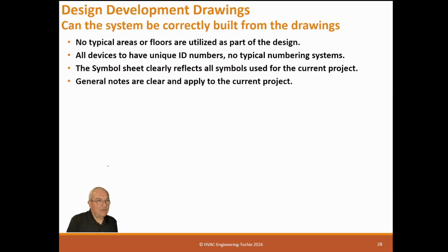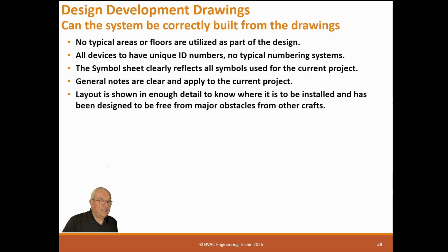General notes are clear and apply to the current project. If they're standard notes, besides the pound-to-fit note, they should be unique for this project. The layout is shown in enough detail to know where it is to be installed and has been designed to be free from major obstacles from the other crafts. So if you design an air handler room, that air handler better fit in the room, or else you've got the wrong room or you've got the wrong air handler in it. So you need to verify that.